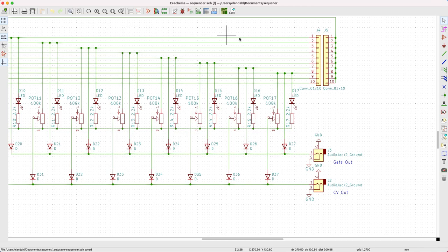There is a fourth wire attached, and it's drawn as going straight through. And each of them goes to an individual connector here, which is labeled J4. So imagine 4 header pins is what I have in mind for this. And each of these pins is connected to one of the outputs. And this is not a signal that will leave the board in the current implementation, although it does in some people's designs. Instead, it can be jumpered across with a small piece of wire to the J5 set of headers here.